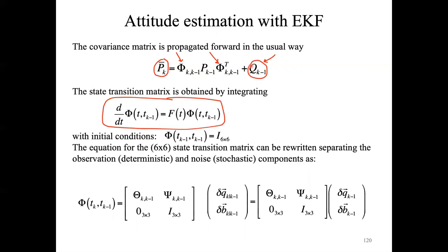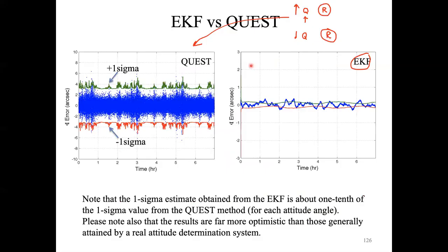What can be done is that after a certain time, you can reinitialize the Kalman filter. What I was saying before means that at a certain time, you restart from a different Q at time 0, while R will be the same because the sensors are the same. So you can indeed update your Q, because you collected data in the previous hour that give you information on the behavior of the gyroscope. So basically, you don't update the Q while the Kalman filter is running, but usually what is done is that it is reinitialized.